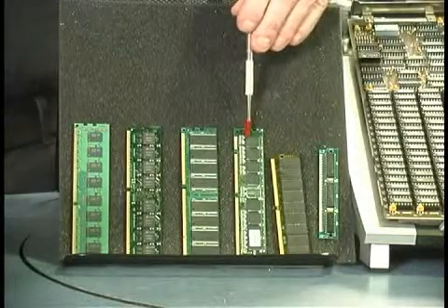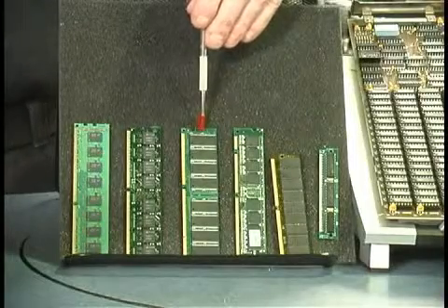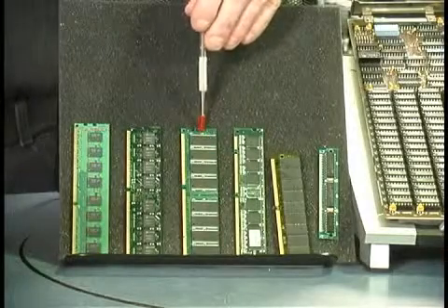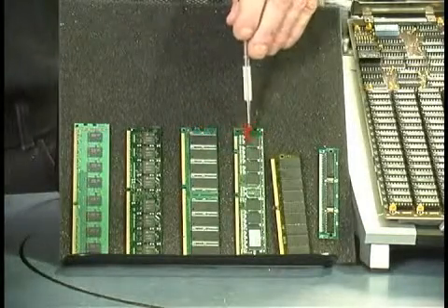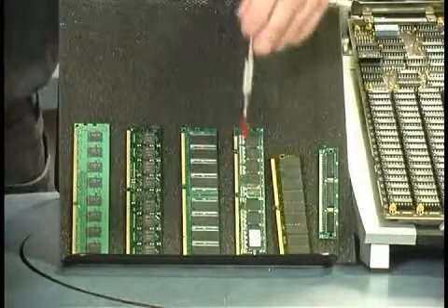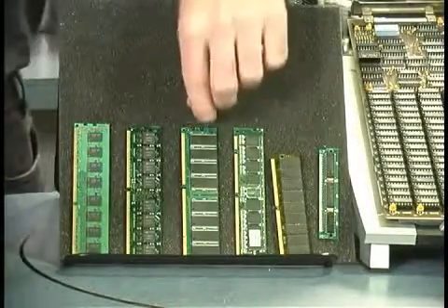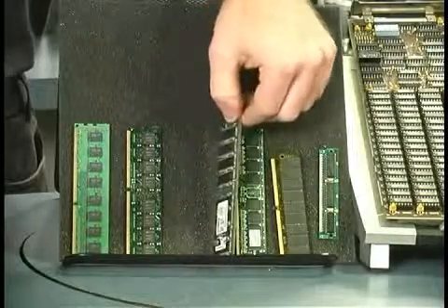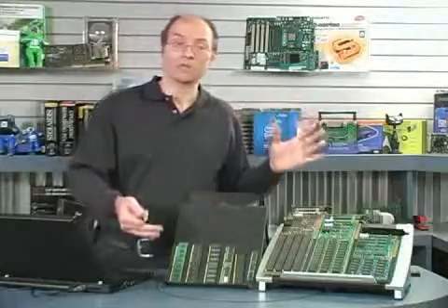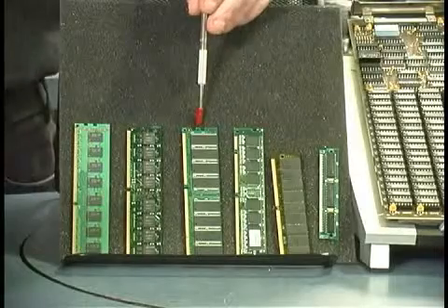Now, starting in 2002, that was replaced by something called DDR SDRAM. The DDR stands for double data rate, and just as the name suggests, it ran twice as fast as the single data rate. So these modules were different. They were not interchangeable, with a different set of contacts. And these were also DIMMs, with the memory contacts on both sides, and they were different. So now we had twice as many contacts without having to have the module be much longer. So this is the DDR DIMM.